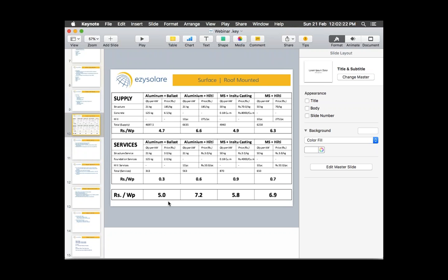Okay. And one little tricky part with Hilti is that Hilti loves doing the design themselves. So whenever you have a requirement, I can share your Hilti guy's number with you. They will give you a very good design report, because their integration with their chemical is very important. What kind of chemical we are choosing and what kind of bolt we are choosing, their compatibility is also one thing. So in that regard, they go on a very case to case basis.